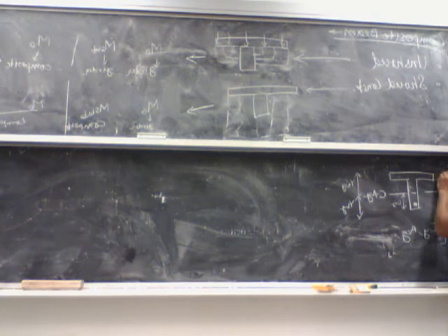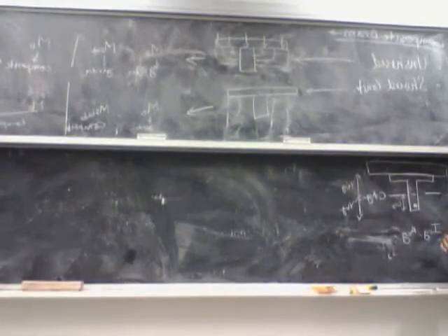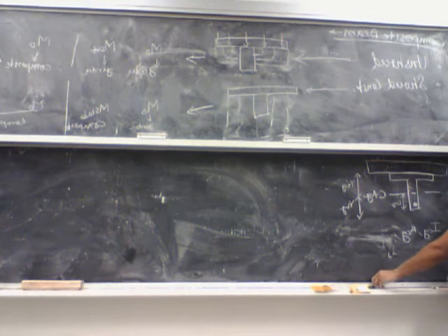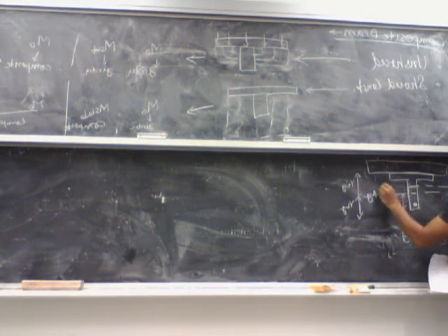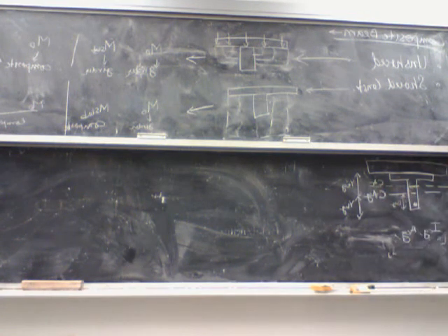And then on top of it, what you have is your composite slab. Once you have the composite slab on it, you'll change the location of your centroidal axis, and it will move up. So this is the centroidal axis of the composite section. For the composite section, this becomes my YTC, and this becomes my YBC.